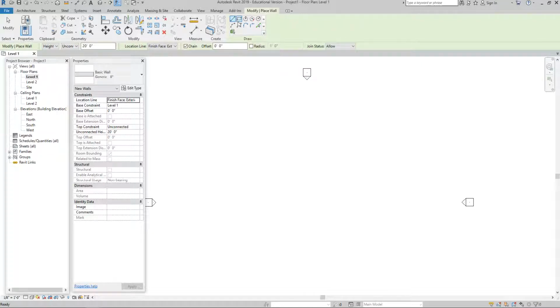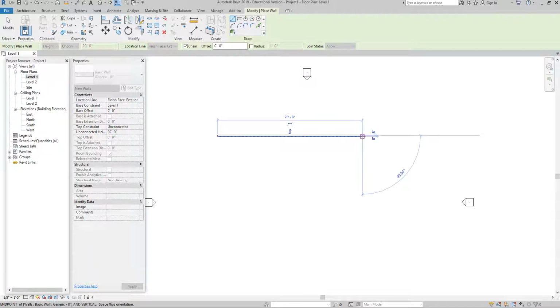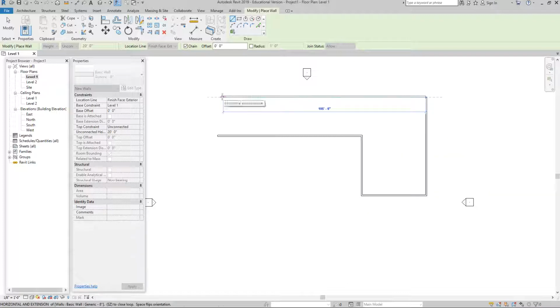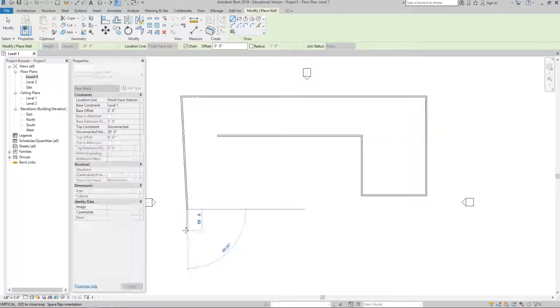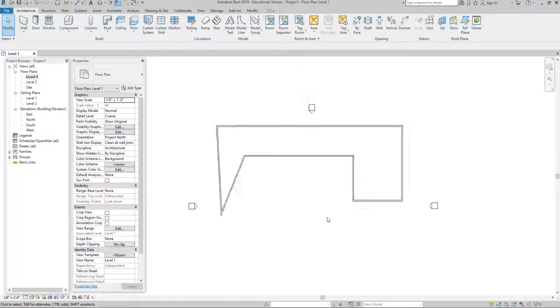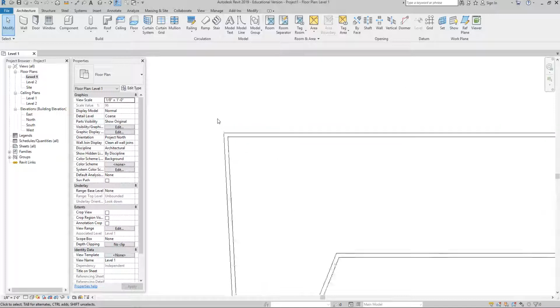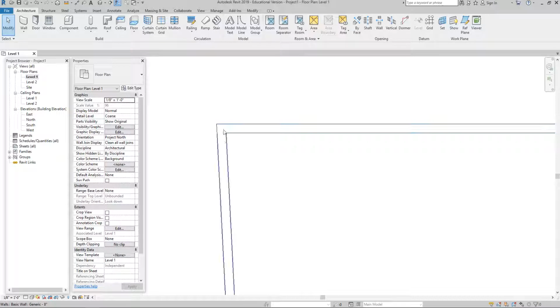All right. So I'm going to click on wall again. And I'm going to click, click, click, click. It's just so easy to draw buildings, right? Oop, there we go. And we'll finish it off. There we go. So also what's nice about Revit, those AutoCAD users, you're going to notice that when I'm drawing my walls that everything nice and neatly joins at the corners, right?